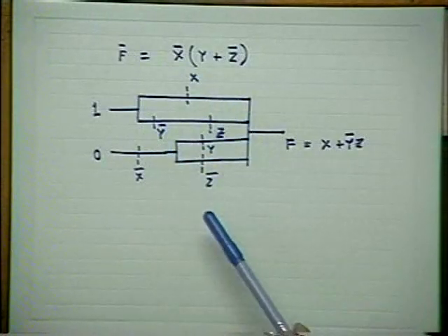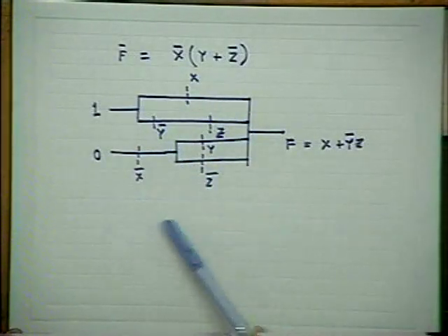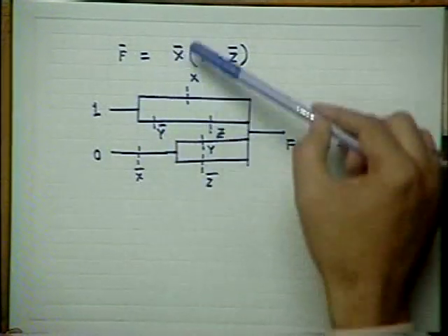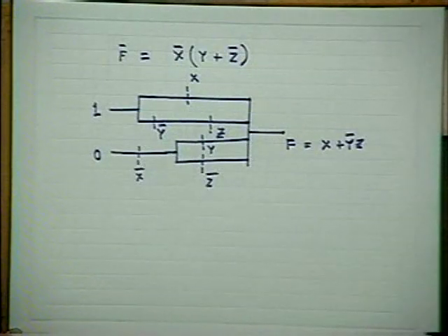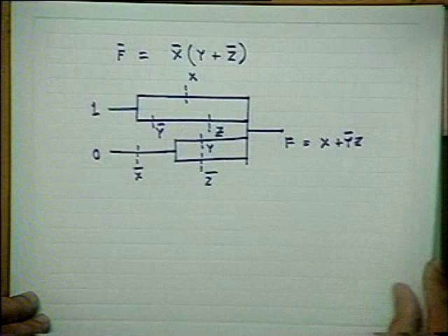You can see that this particular approach of pass transistor logic can be considered as a structured logic if I draw the corresponding stick diagrams now. What is the difficulty of this stick diagram? You are showing all inputs at different points and all these things. We have to connect all the inputs at one end, and output on one side, and maybe power supply and ground. Okay, but here I have drawn it in such a way. What I have to do, therefore, is extend this, and so on. Actually, if I want to connect all X, Y, Z, etc. at one side, I have to bring all these poly connections to one end, and exactly that is done. And what is actually done to make it more symmetric, more structural, is as follows.